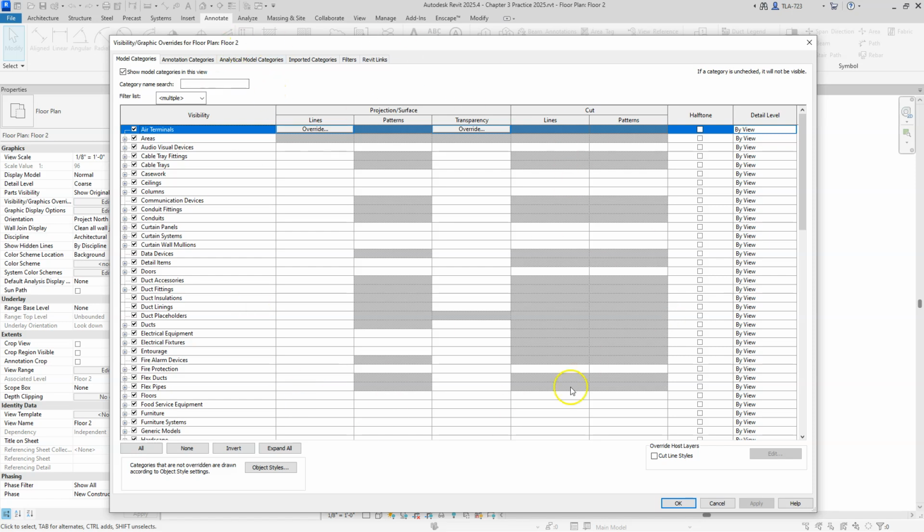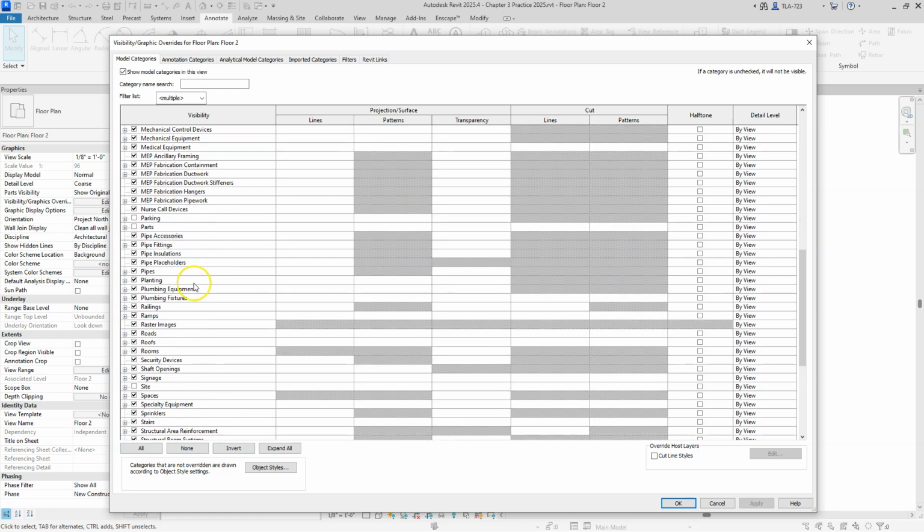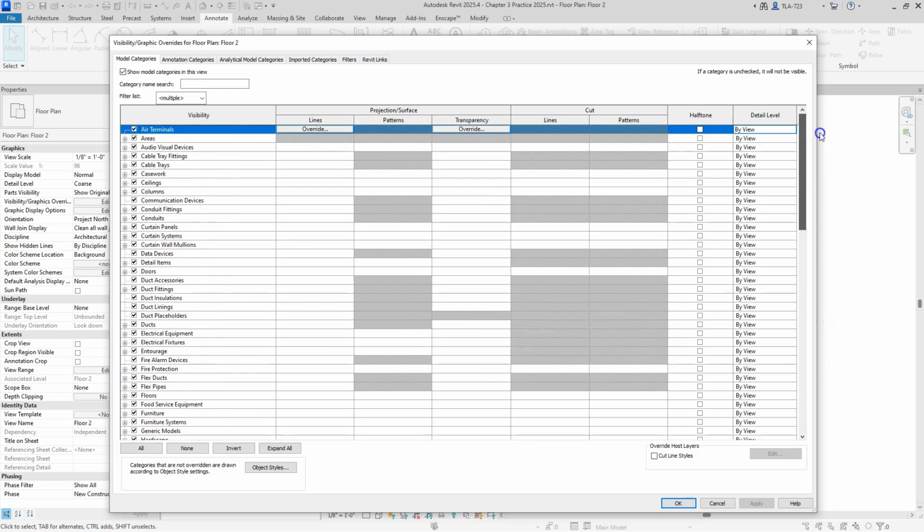It will retain its size and shape on subsequent opens. But you can see over here on the left you have the categories of the objects, and there's a lot of categories you have in any given Revit model. Revit categorizes the model objects within it by type intentionally so that we have this control not only at the object level, the instance level, but also by the category level. So in other words, we could hide the display of all of some type of object that belonged to a certain group, like doors or windows or floors or ceilings.